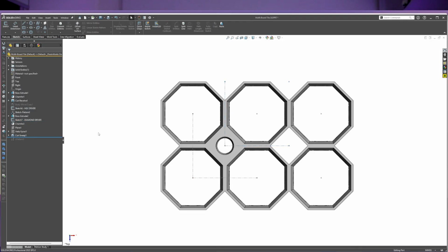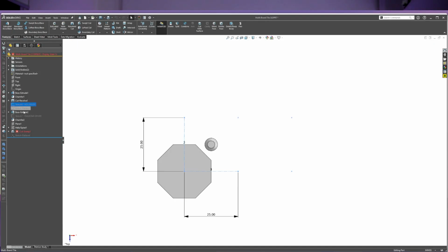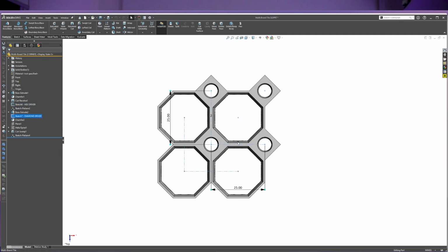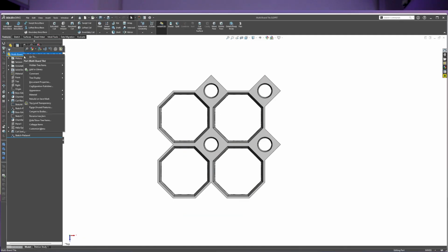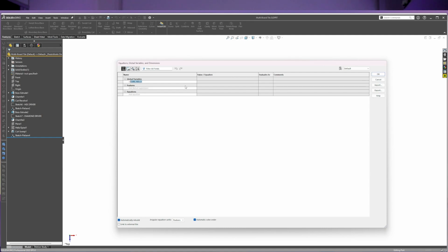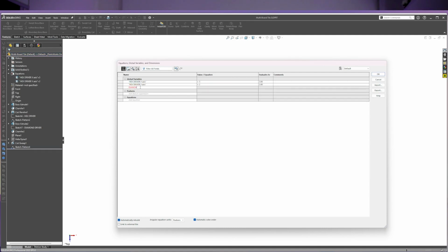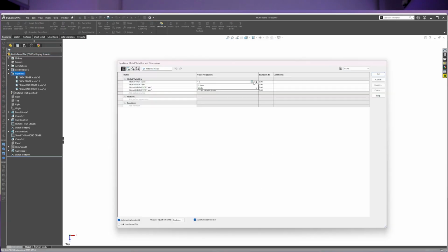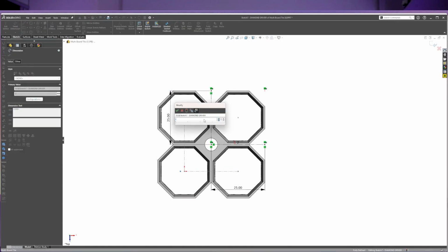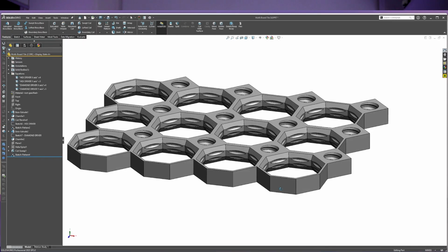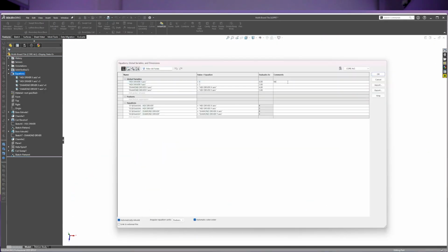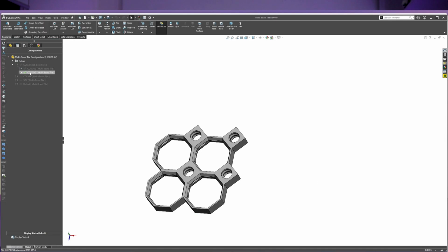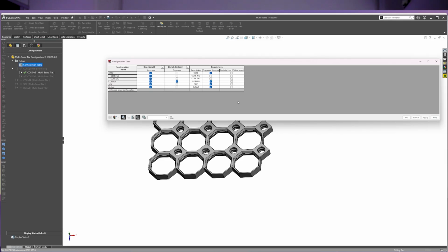All right, so the last step, once I created those features and I was very confident with the accuracy of those first 4 features, now becomes a question of configurations and patterns to create, firstly, the 3 different types of tiles, where you've got, let's say, a corner tile, which doesn't have those spikes on it, a side tile, which has spikes on one side, and the other type of tile which has spikes on 2 sides. So this is the 3 types of tiles that Multiboard comes in.